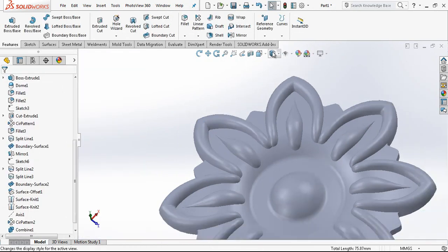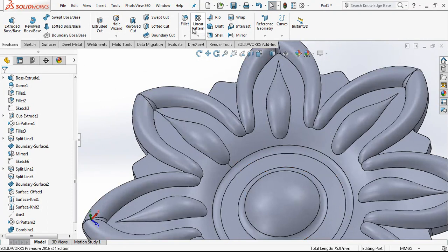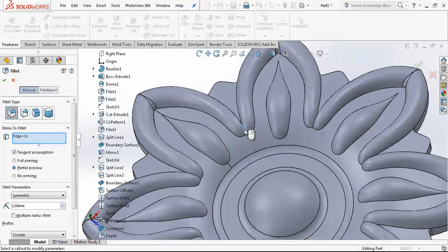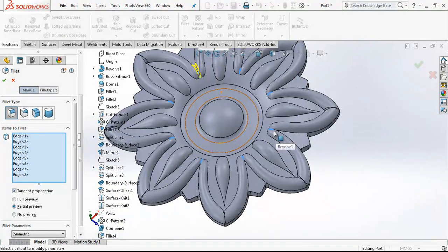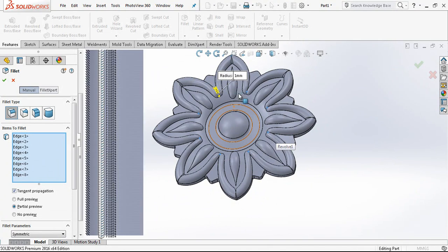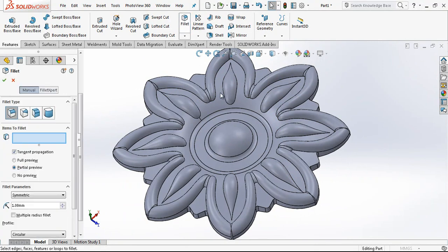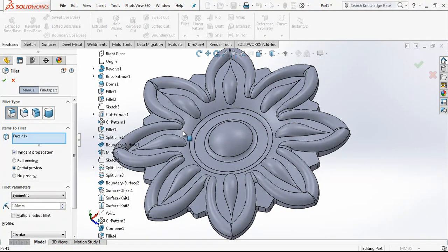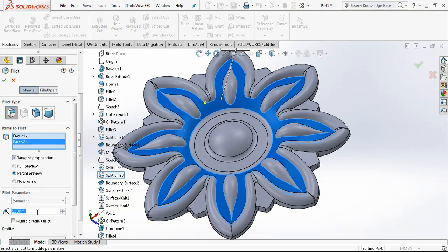This radius is done. Just a little radius, in fact, yes. And now this part of the body will be, yeah, nice, a radius. And after I will just give a complete radius inside, a small radius relative to the other ones that we made, 0.5.